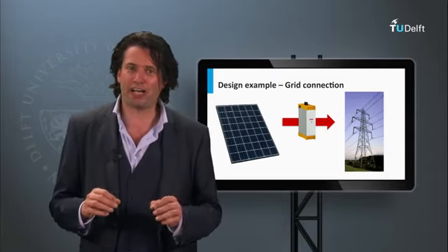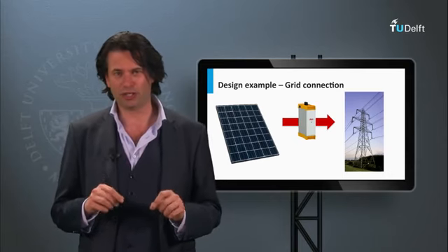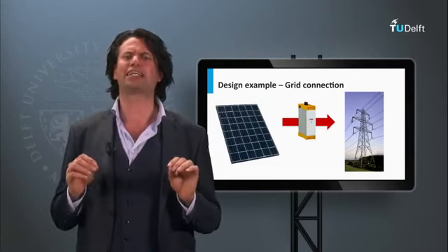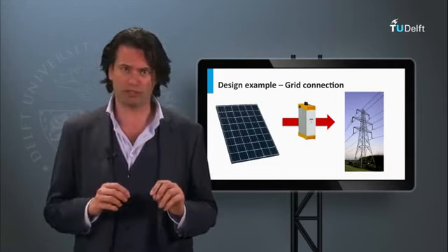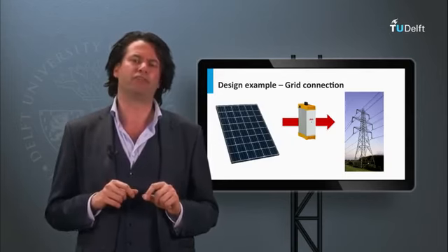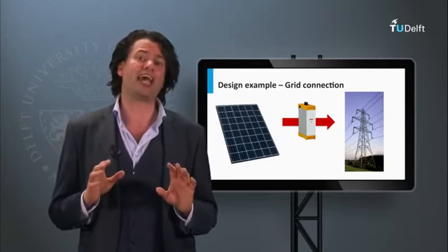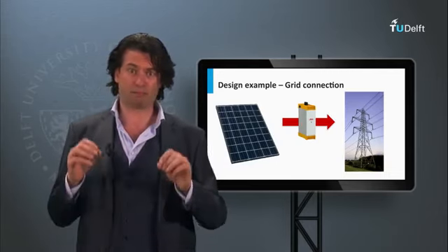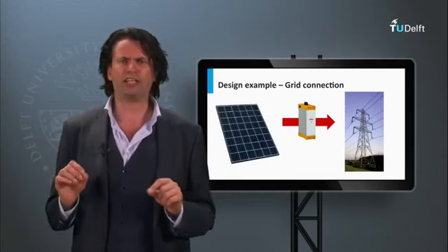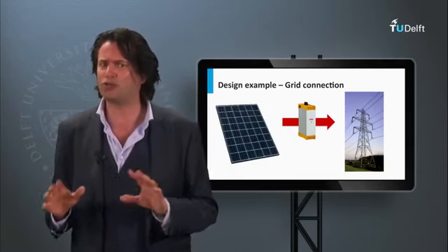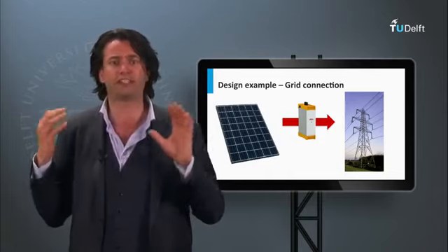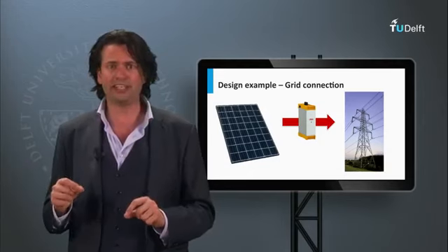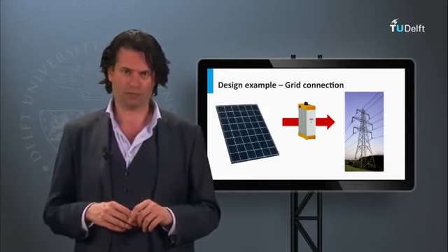Now, I must clarify one thing about the grid-connected PV system. Usually, the amount of PV panels or the rating of PV panels need not be exactly as per the load requirements, like it was in the standalone PV system. This is because any excess or deficit of PV power can be compensated by the grid that is present in the scenario anyway. This was not true for the standalone system, as any surplus or deficit of power had to be met with a variation in the storage size, leading to considerable system costs.